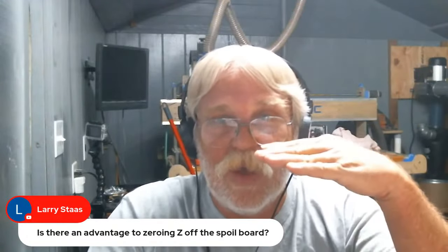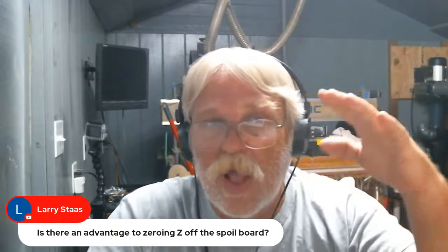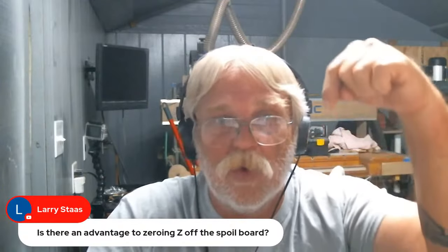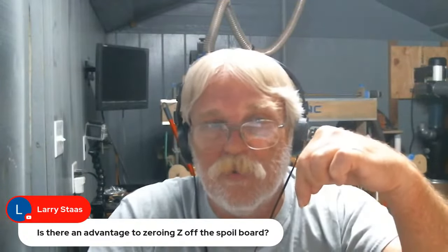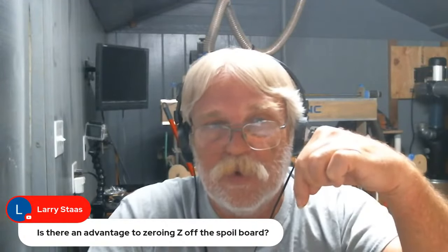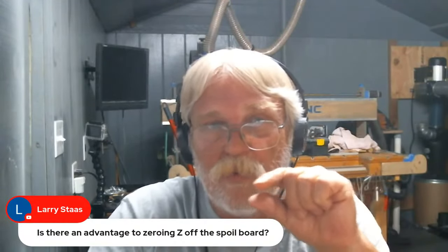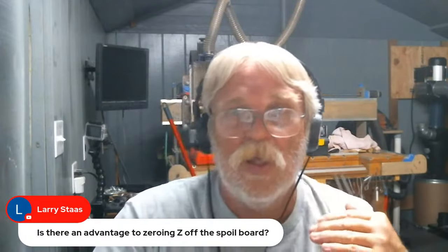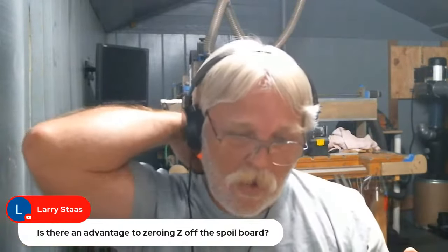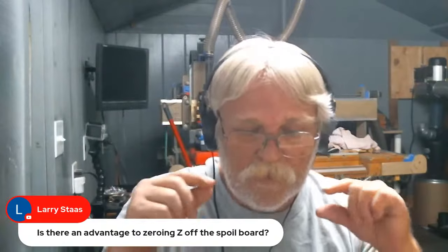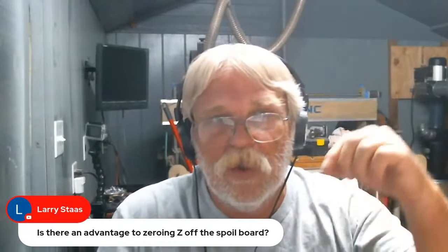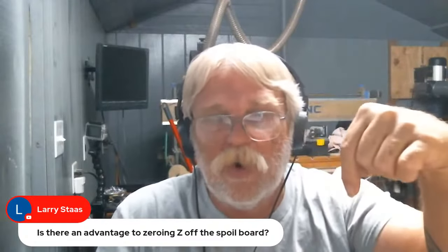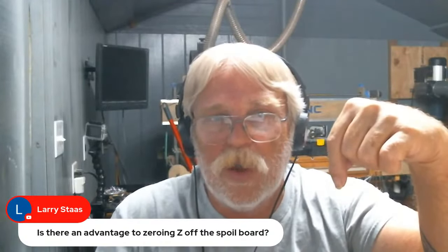That way, it doesn't matter how thick your material actually is, it will machine that pocket down to 1/4 of an inch above the spoil board, leaving that 1/4 inch remaining. So if that makes any sense, if the critical measurement is depth from the surface, then setting Z0 from the material surface is the way to go.